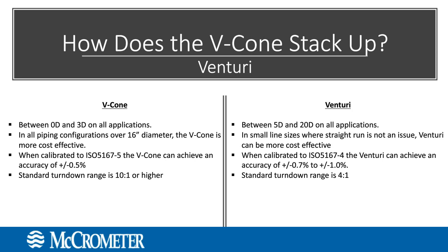Next, let's take a look at the Venturi meter. So kind of a similar DP concept. The VCone, I kind of like to say, is sometimes like an inside-out Venturi, whereas the choke point in the Venturi is built into the ID of the pipe. We make that choke point suspended as an obstruction in the center of the pipe.